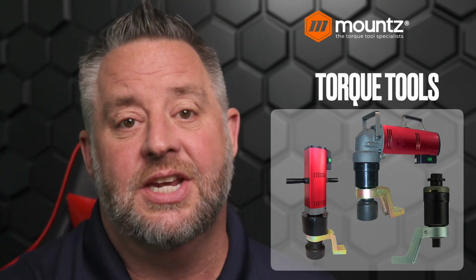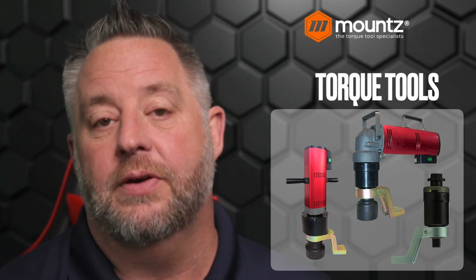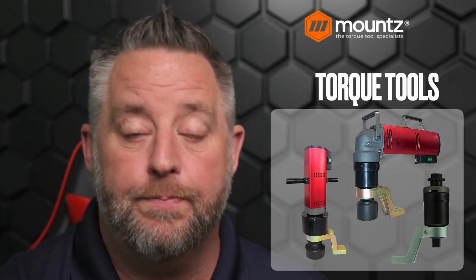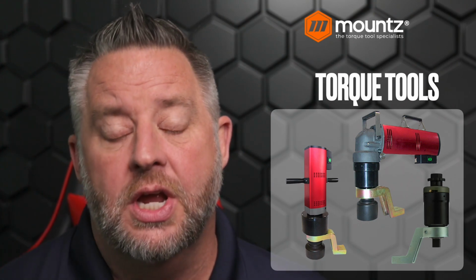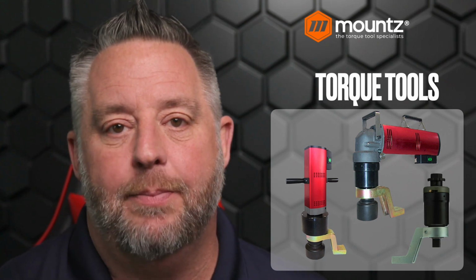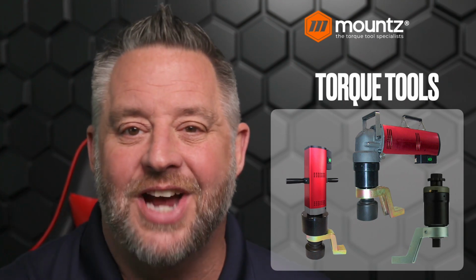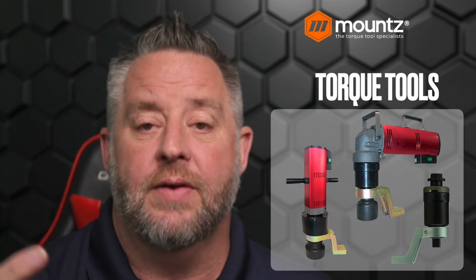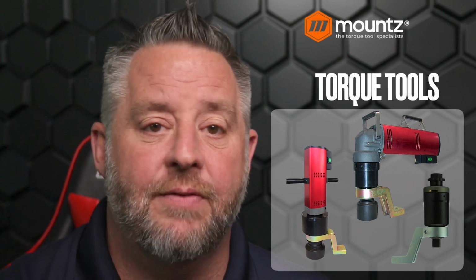And this is what is going to be generating that massive type of torque that we may need to, again, stretch a bolt at a really high torque value to be able to create the tension that we need to make sure that bolt is available. And so we do have different styles. What you see here are electric versions. So we have an electric motor that is giving us our input, and then we have a gearbox.